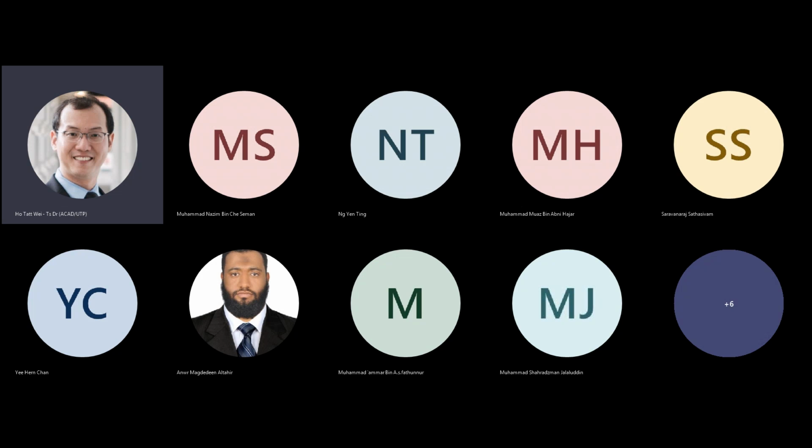Okay, so the first basic concept is basically how do you assemble digital logic gates from these basic transistors. That's the first part, chapter 1, that is basically covering, right? And it's this idea that we are going to actually assemble the logic gates using a pair of switches. Okay, that's why it's called complementary metal oxide semiconductor, right? So you have a switch that is a PMOS transistor, and you have a switch that's an NMOS transistor.